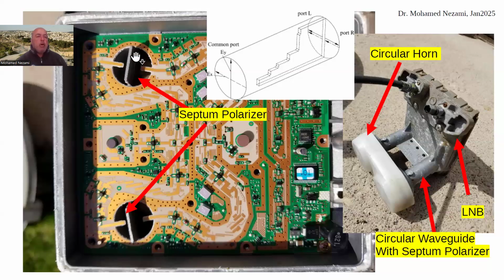Basically, you can't separate the electronics in here from the feed mechanism, because you're trying to get the signal with a probe. You can see that probe is connected right to the GaAsFETs in here. This is a GaAsFET low noise amplifier. Even the DC is fed to the gate of this one, in fact the DC is on the board in here, because you want to preserve the signal and not have any kind of losses. And the same is done here.